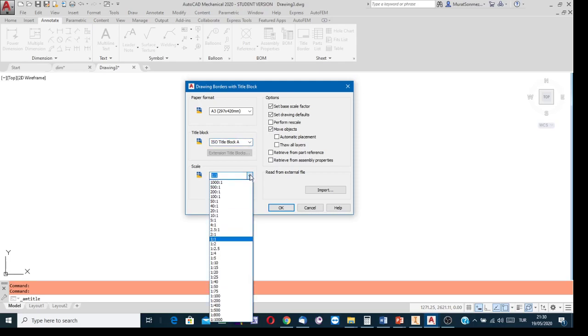Select the drawing scale. If the object is a little one, while the size of the object is comparable with the working space of A3 size paper, you can select 1:1 as the drawing scale. But if the object, for instance, is a house and the paper is A3 size, you see here the standard size for A3 size paper, 420 millimeters by 297 millimeters.